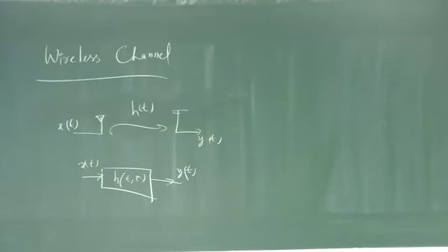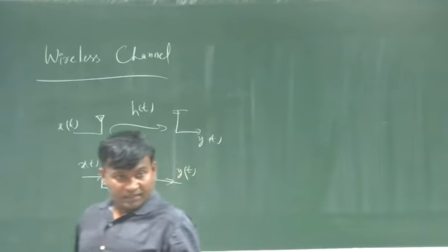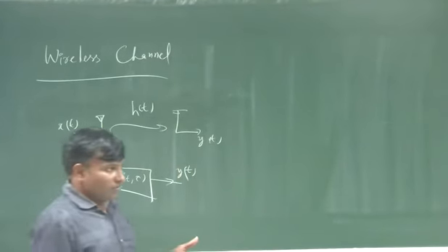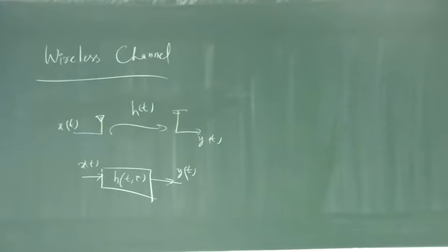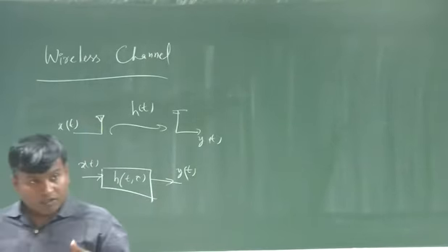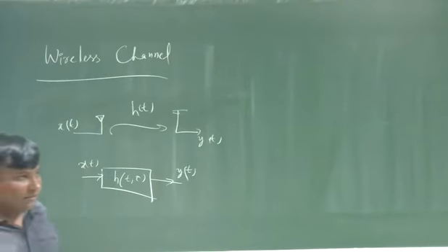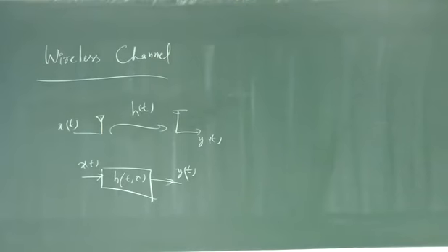So what causes these variations? Well, multipath is inherent to wireless systems, and there is always what is called Doppler, which we will talk about. Doppler causes time variations. Even if the user is stationary, you can still expect the channel impulse response to vary because the surroundings are not stationary. Always some movement.